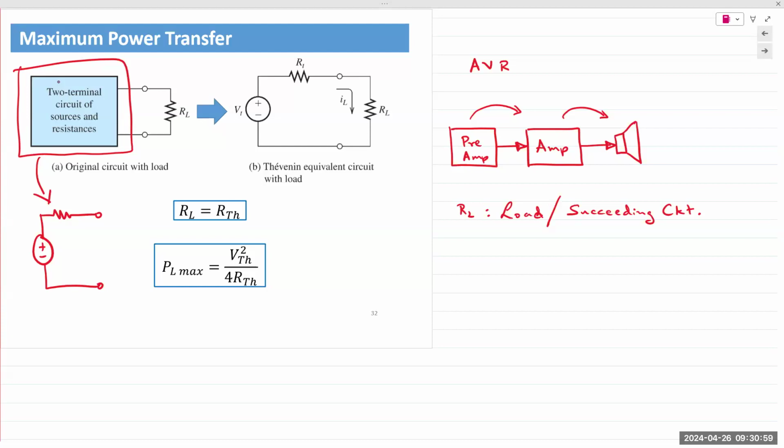Yes, you can. If you're dealing with current sources, yes. It wouldn't be divided by exact. You'd have to derive it and then do the equation, because for current, P is equal to I squared times R. For voltage, it's V squared divided by R. So the equation would be different, but the principle is the same. Question being asked was, can we use a current source or Norton equivalent and do it? And the answer is yes, we can.